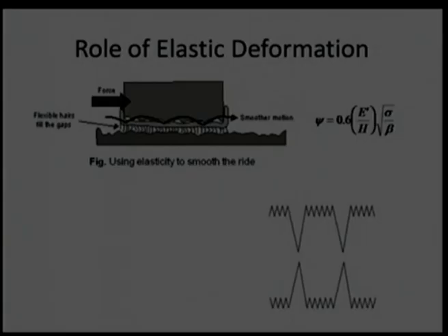That will lead to a reduction in the service life. Then another one is Young's modulus. It's interesting to note that we are emphasizing low Young's modulus. Low Young's modulus will reduce the plasticity index. In general mechanical engineering and other streams, we generally prefer high Young's modulus, but from a tribological application point of view, we prefer low Young's modulus.